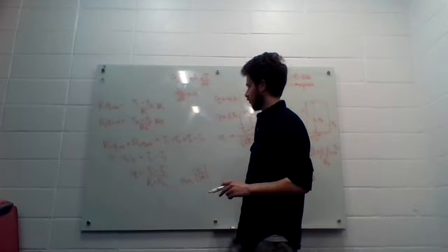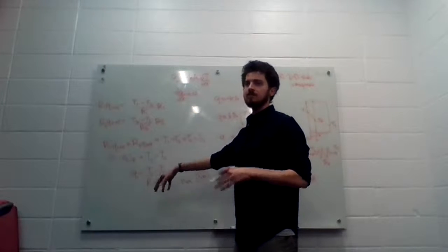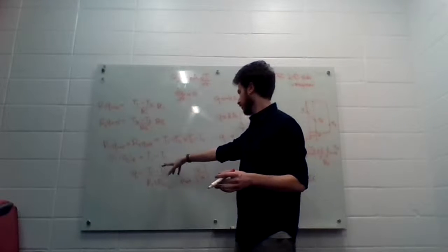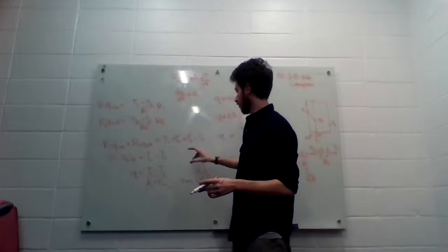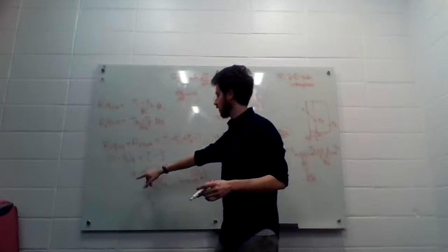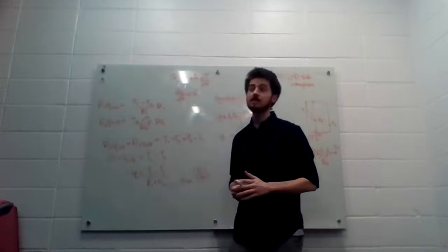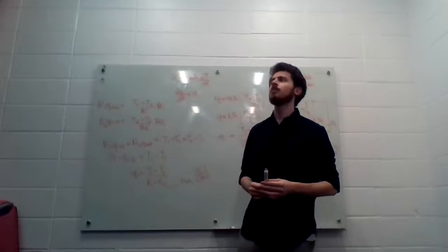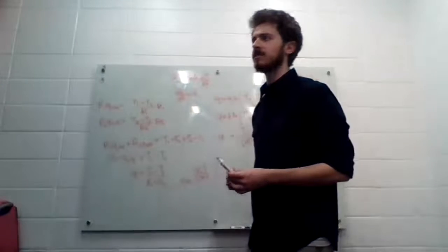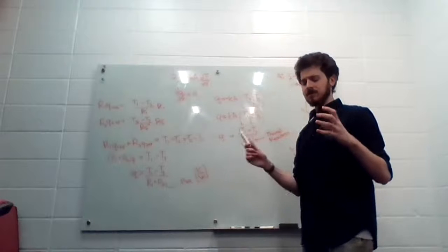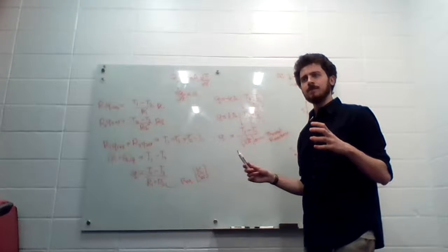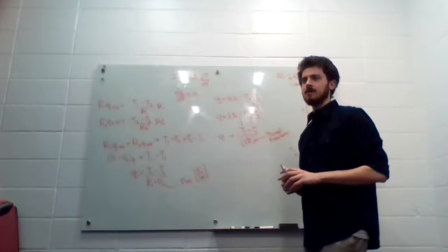All right, yeah. So you've got temperature up here, Celsius, Kelvin, doesn't really matter because you're doing a temperature difference. So it's Kelvin over watts. And when you divide, you end up with watts, which is what we wanted. When you talk about R values for a wall, units are a little different. If you've got a really heavy duty wall with insulation, you might have something like R20.